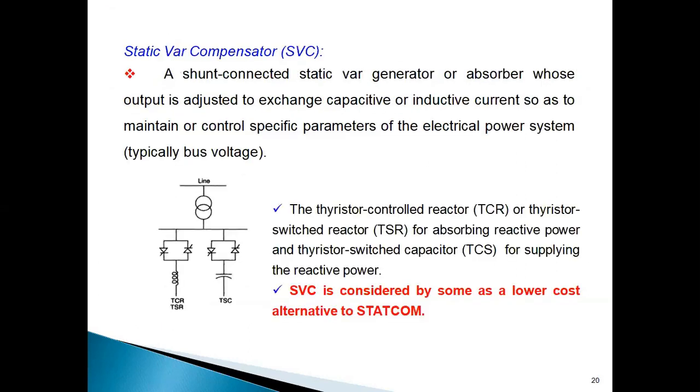Okay, fine. Now SVC, this is another example of a shunt FACTS controller, static var compensator. So it can also absorb and generate reactive power. We'll be seeing the comparison between the StatCom and static var compensator. When compared to SVC, StatCom is expensive, but future-wise it is superior. StatCom is superior to static var compensator. So static synchronous compensator has superior features when compared to static var compensator. StatCom is better than SVC in performance aspect. How that is justified, we will see later with the help of VI characteristics.